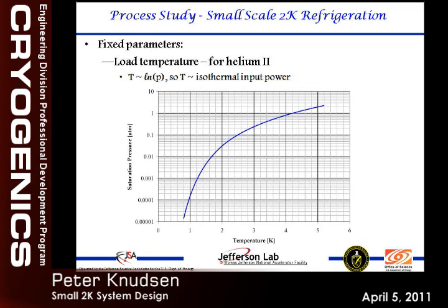The pressure ratio in this case is essentially 1 divided by whatever your saturation pressure is, and for us, that's about 35 millibars. So we're looking at roughly a compression ratio of 34. That places us about here on that curve.